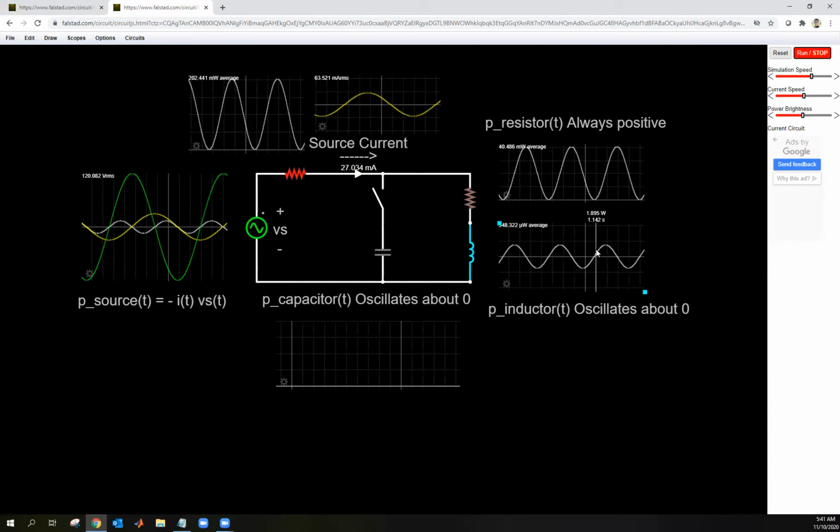And so PG&E would not like that. You would not like that because PG&E would charge you some more money. Well, what you can do here is click on this capacitor, and hopefully these currents go down. So PG&E is happy because these currents go down, and you're going to see that the power factor goes to 1, which means the current and voltage now become in phase.